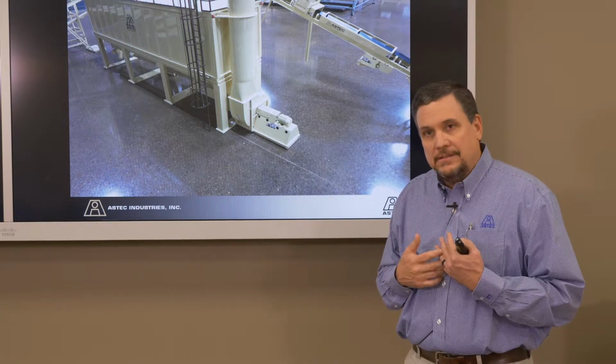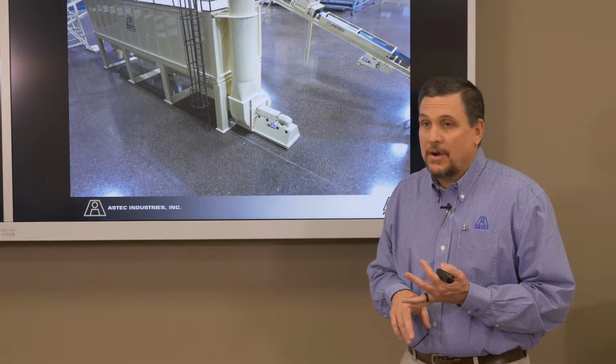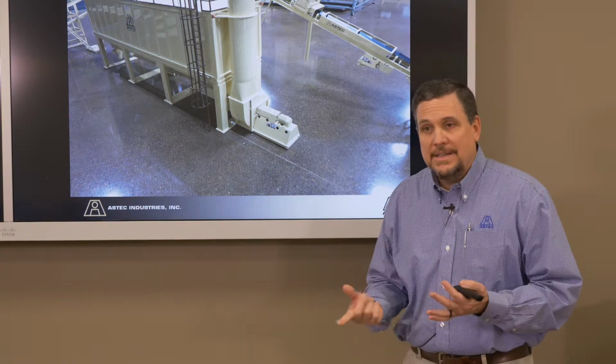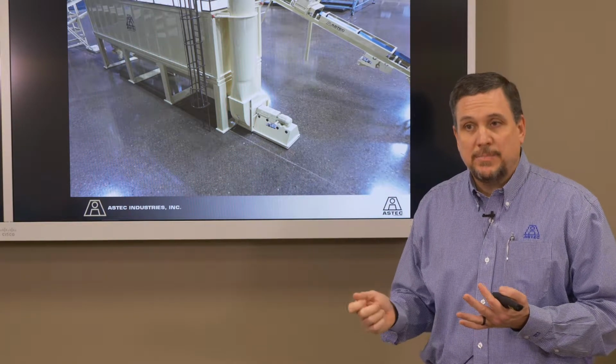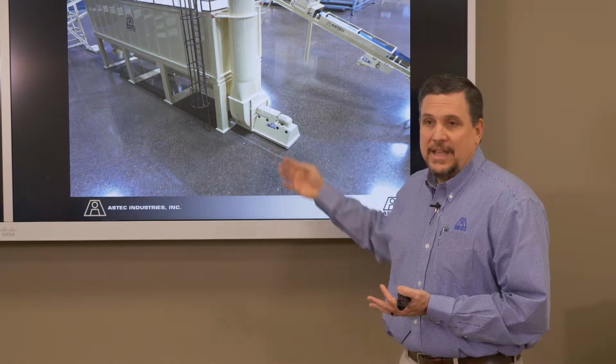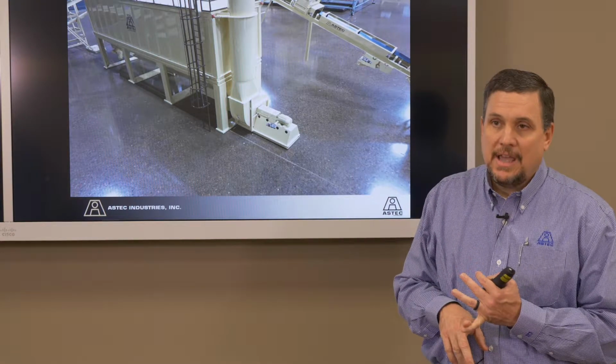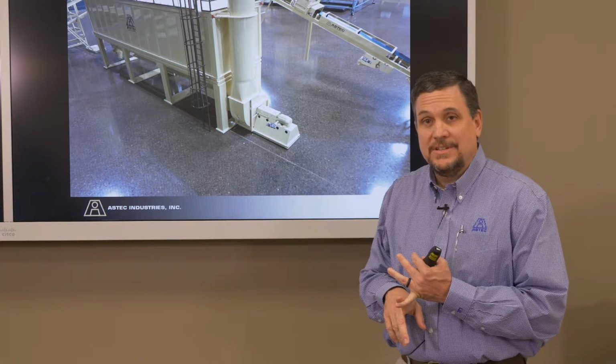VFDs are utilized throughout the plant. They're used on the coal feed bins, and those VFDs are just like that in a drill, basically where you want to adjust the speed by just speeding it up and slowing it down. So they're able to do that on the exhaust fan. It does 2 things. It reduces the noise tremendously, and then it also saves energy.